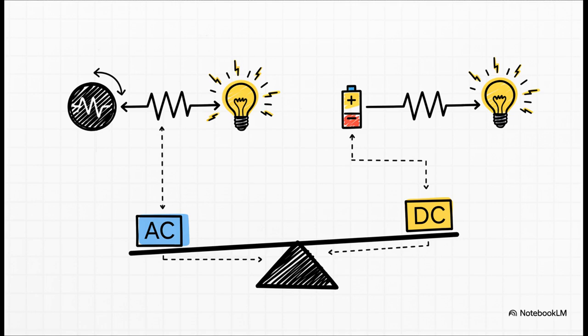This single sentence proves that at the end of the day, all that complex integration, all those wild sine and cosine functions, they just bring us right back to a simple, balanced energy transfer. An AC wave pushing through a resistor does the exact same amount of real, tangible work as a steady DC battery of the equivalent RMS voltage.